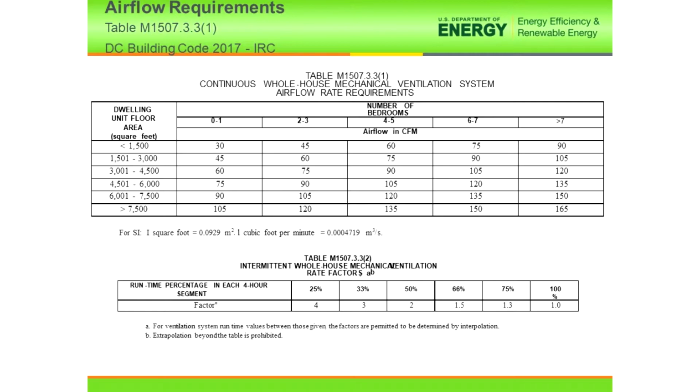Now, the unit on the top floor, that's only serving the top floor or the second floor, its whole house ventilation rate is based on that square footage and the people that reside in that portion of the house. So combined total, they will make up the whole house ventilation rate, okay? So you can't bring in the whole house ventilation rate on both systems because it's going to be too much, okay? You have to balance that rate per system based on the areas that each one of them is serving, okay? So just keep that in mind. This is very important now.